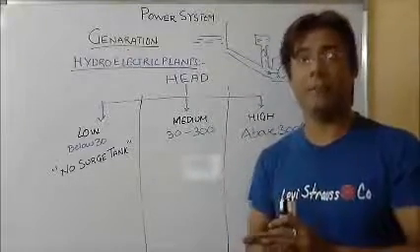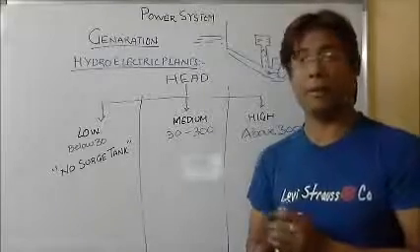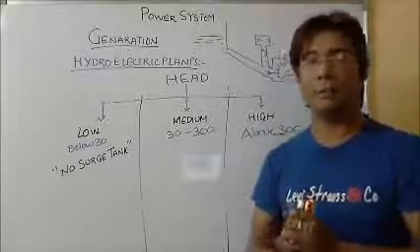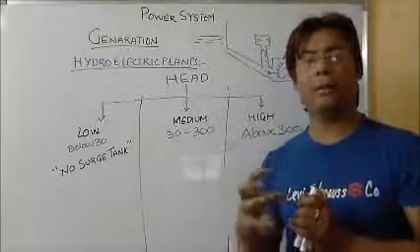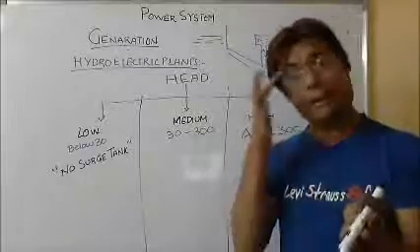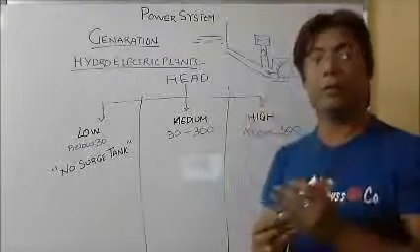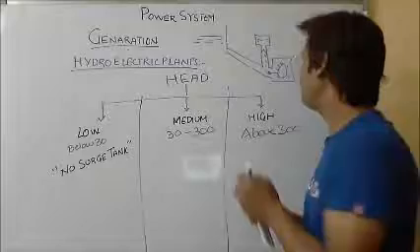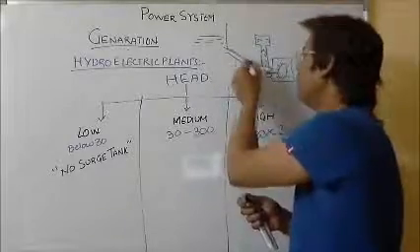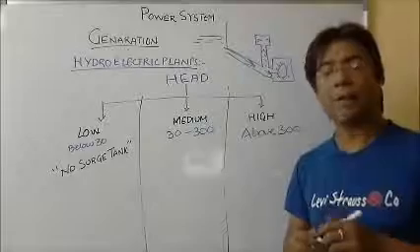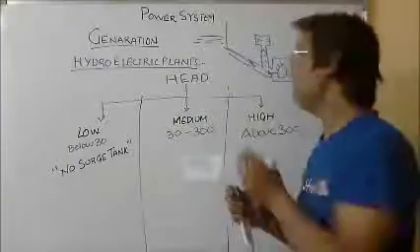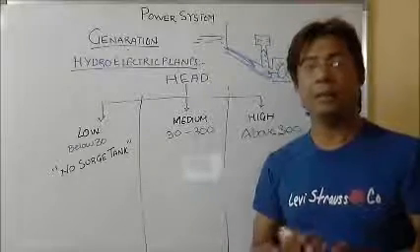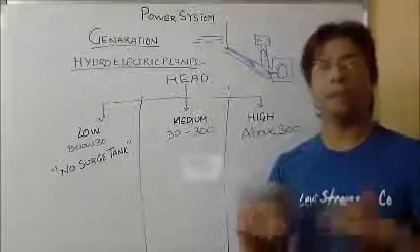So we can understand that during a load rejection period, the rejection will be reflected in the mechanical part also, so the turbine will try to close its gates. When the turbine tries to close its gates, the water coming from here will have a high pressure and it will press on this penstock, and if this penstock is not able to withstand the pressure hammers of the water, then it will explode.